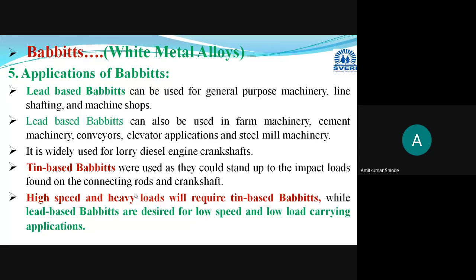Lead based babbits are used for general purpose machinery, in machine shops, in line shafting, wherever bearings are lead based. These can also be used in farm machinery, cement machinery, different conveyors, elevator applications, or in steel mill machinery. Lead based babbits are there.